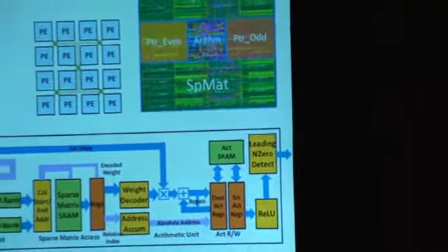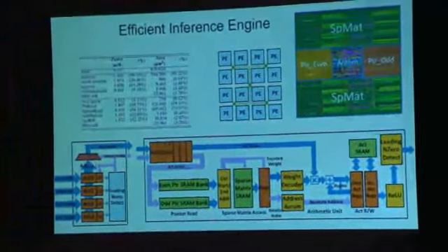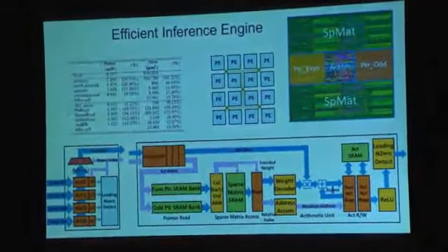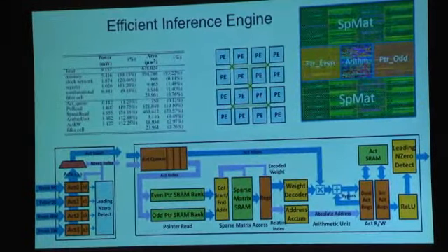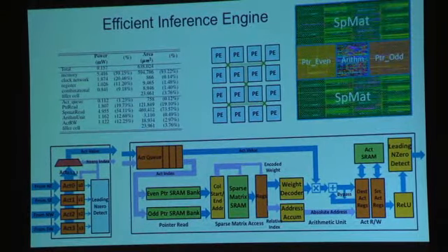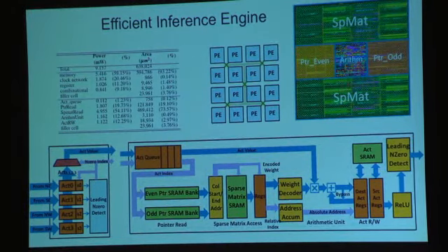In the compressed sparse row, we use a compressed sparse column format. We store a pointer. So we have a big array of non-zeros, and then we have a big array of how many zeros are between the non-zeros. And we have a pointer to that pair of arrays. They're one-to-one, so we only need one pointer for every column. So that basically says where in the array that column starts, and then we basically have, in addition to the weights, the spacing to the next weight.